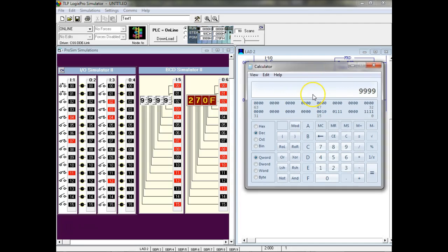So what this does, it gives me the ability, in an outside world, to deal with the decimal number system, even though my computer is dealing with binary, right? Y'all understand that? So I'm over here, I want a motor to run at 200 RPM. I put in 200, right? But bringing that into a PLC would mean nothing because the PLC is dealing with a binary world, right? So I have a method of taking binary and converting it to decimal so I can display and send information so I as a human understand it, right? Because I know the decimal number system.